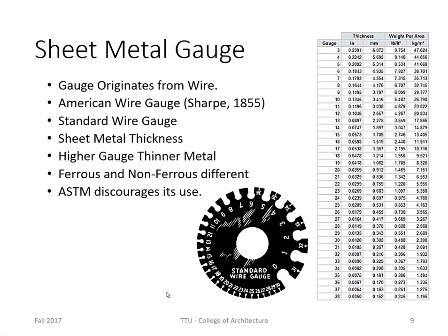So if somebody says, oh, this is 30 gauge, versus maybe you asked for 26 gauge and they say, no, we're going to give you 29 gauge. Okay, then that means they're giving you a thinner material. If you wanted 26 gauge and they say, okay, but all we've got is 22 gauge, that's a lower number, but it's a thicker material.